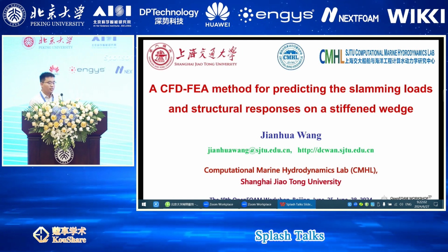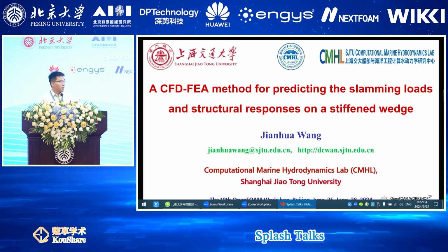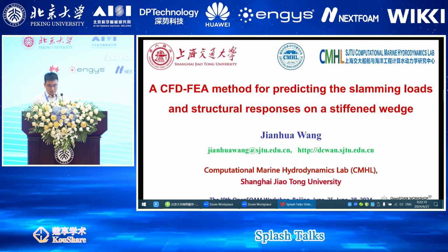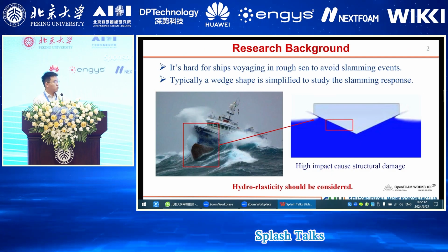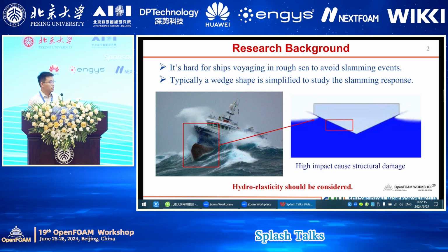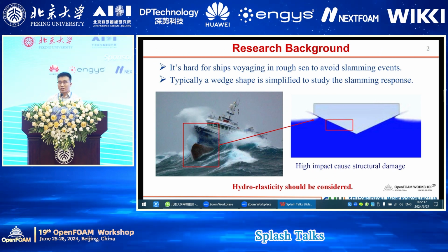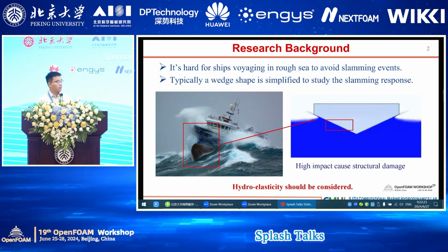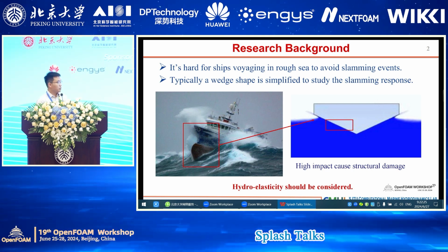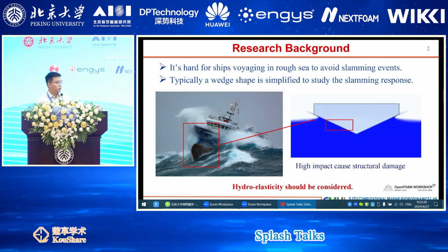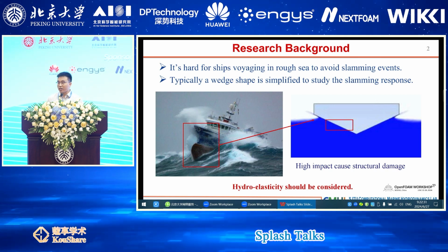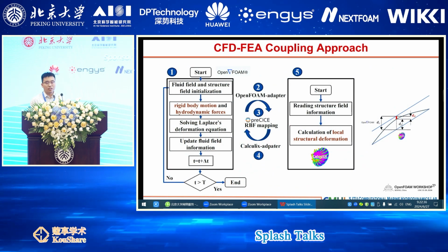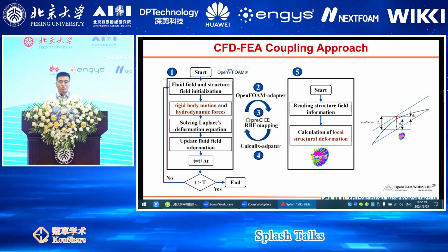My talk is about the FSI method for predicting slamming loads and structural responses of a stiff wedge. As we all know, ships will experience slamming events, and mostly we simplify this kind of study to a simplified wedge-shaped water entry problem, in which case hydroelasticity must be considered.